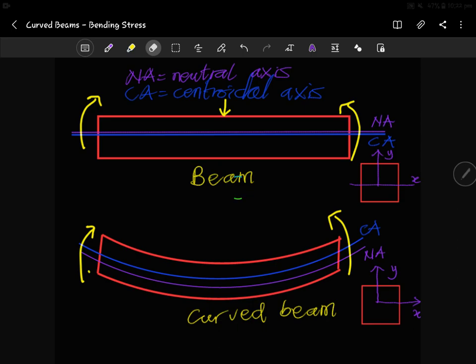If we see that position within a straight prismatic beam as a neutral axis, we are saying that for a particular loading system, that position within the beam experiences no stress at all. The loading applied to the beam has no effect at that position. That's what we mean by the neutral axis.